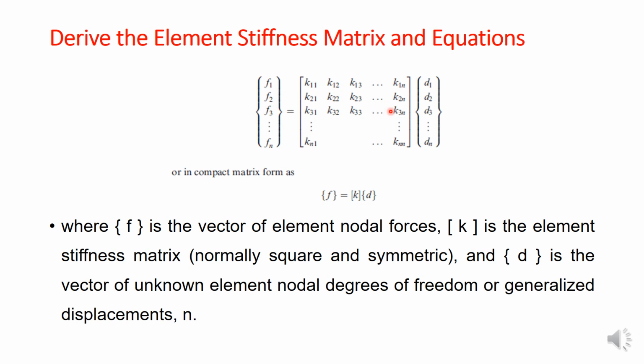You will understand how we find this stiffness matrix when we go and see the problems on beam and bar elements. There you will understand clearly the significance of each of these influence coefficients. These K11, K12, etc. are called stiffness influence coefficients. You will understand how the values of K11 or K12 are derived when we discuss problems on beam and bar elements.